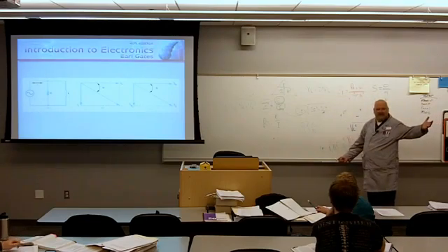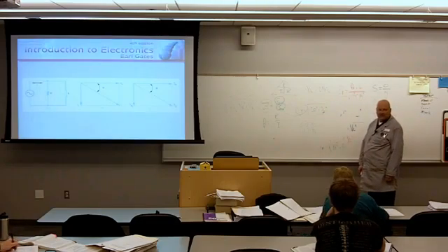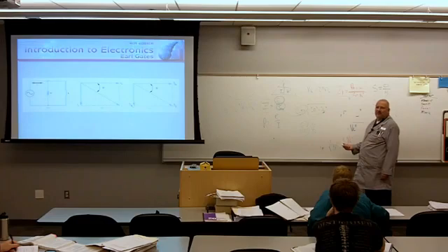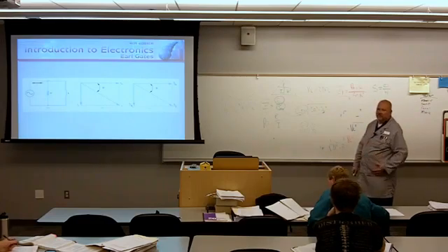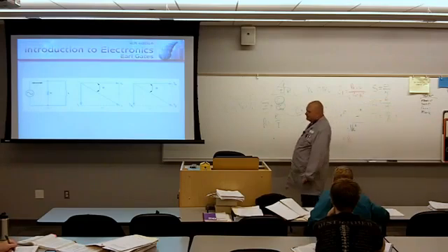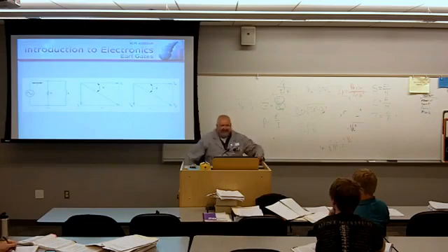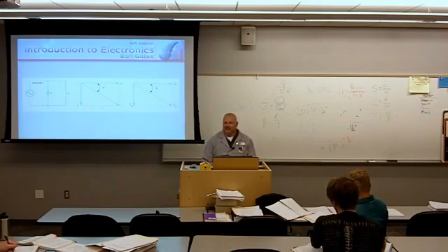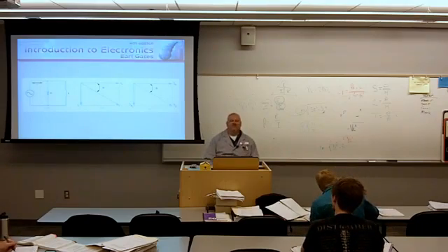And you already know how to do it, because in DC you all remember this formula, product over sum. So no longer are we dealing with the product over sum, but now the product over the vectorial sum. If you really want to have fun with Z, calculate it this way. And if you don't do it this quarter, that's fine. We'll get to you in third quarter, and we'll have you do the formula then. Either way, before you graduate, we're going to have you do this formula. Might as well use it now. It's another tool in your box. Make sense?